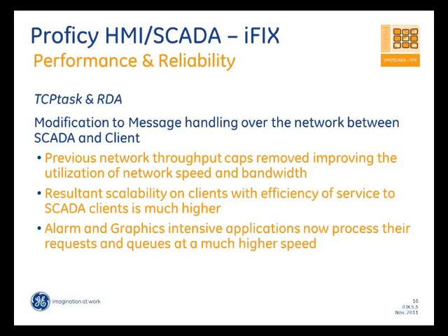What that meant was any customers who had a heavy application in terms of alarms, or a heavy application in terms of number of clients, or number of animations and refreshes that were happening on the clients that required the SCADA to keep on serving the clients, used to find out that either they faced client dropouts, or the alarms used to come a lot slower, or the whole performance used to go down as they added clients. Now with the new TCP task, the ability for the TCP task to handle network transactions has gone up.